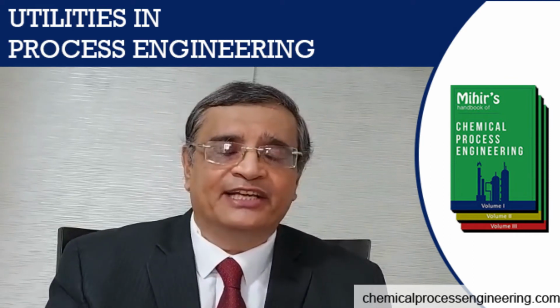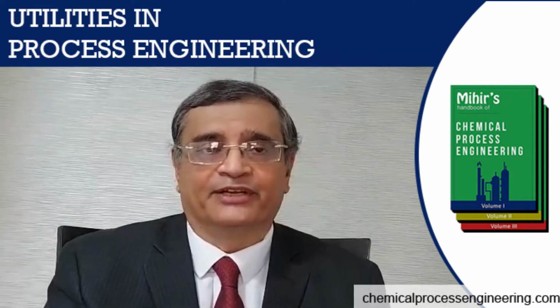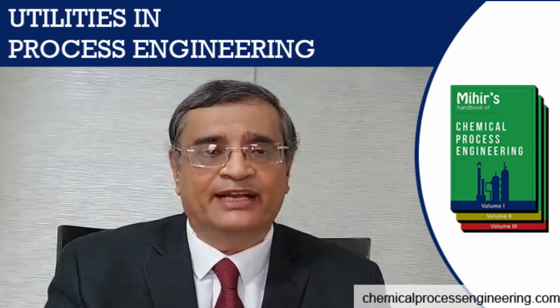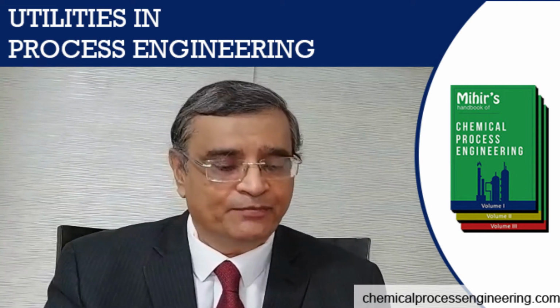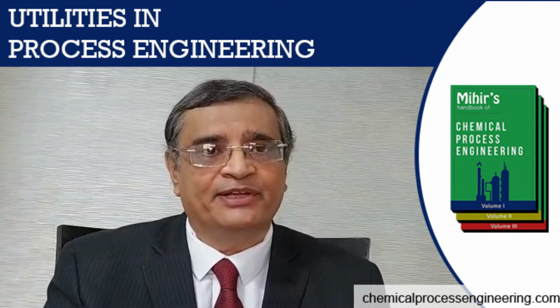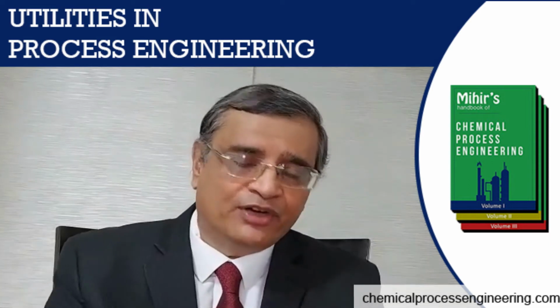As far as utilities are concerned, the first document used for the design is the process simulation. In the process simulation, process flow diagrams, and heat and material balance, the requirement of utilities is identified: at what approach temperatures, what are the requirements, etc. And after that you end up with the process design basis. The process design basis also gives the specification of the utilities, and then you take each system for further design.